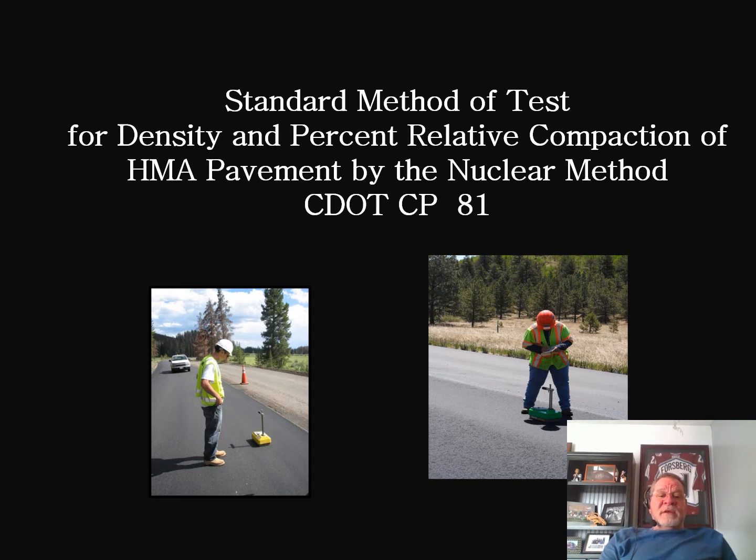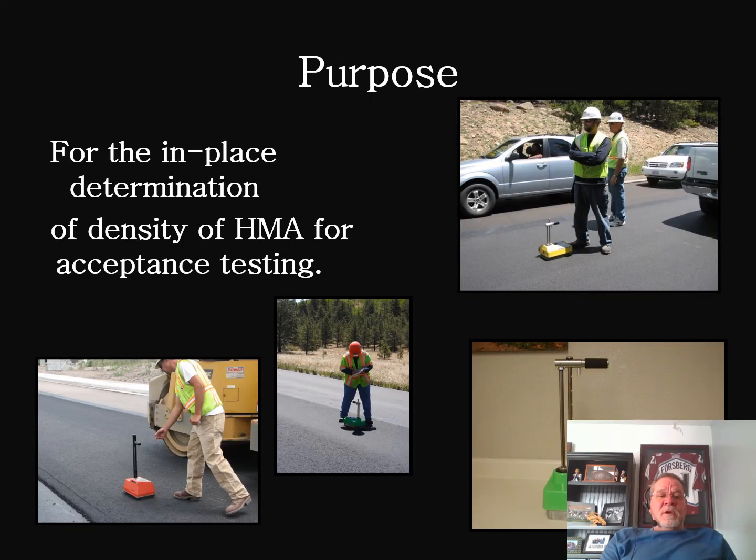Talk about density and percent compaction of a compacted mixture using the nuclear method, which is CDOT CP81. We're going to do the internal or in-place density of materials using a nuclear gauge.